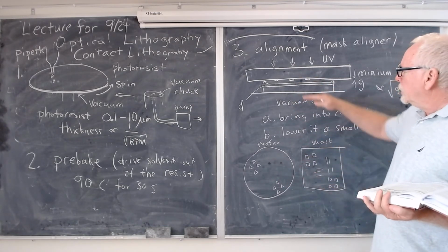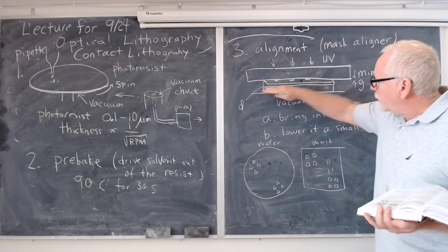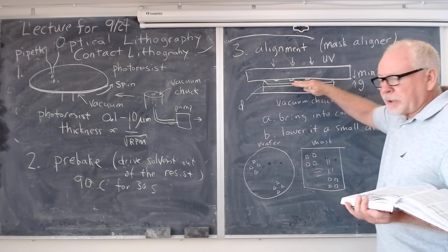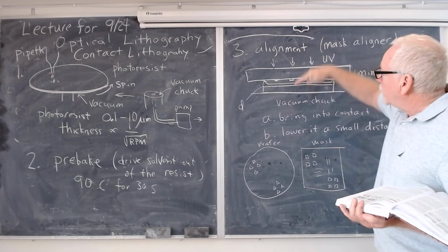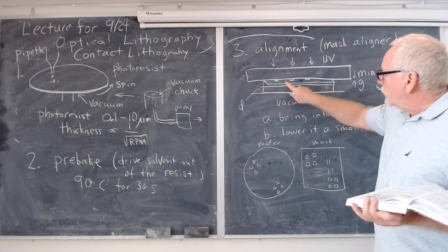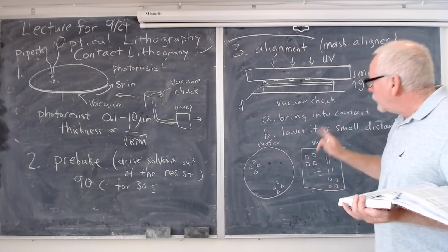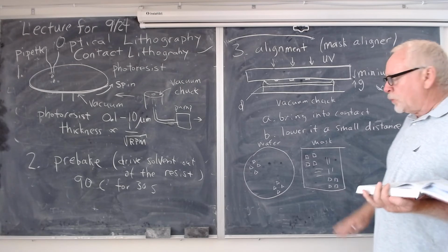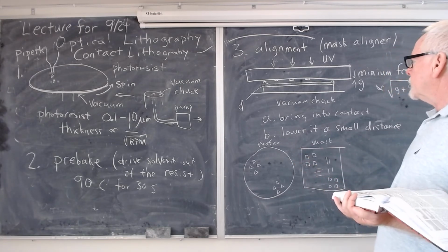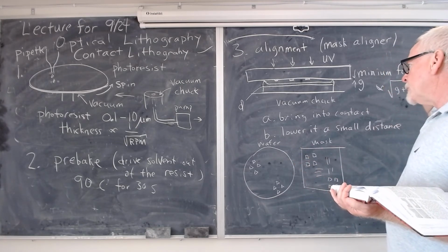Now, in real life, once you have it lined up, ideally, once you have your wafer lined up, you just bring it up and back into contact, and then you do your exposure, and it's exposed properly to make your features wherever you want them, properly aligned with the rest of the steps.